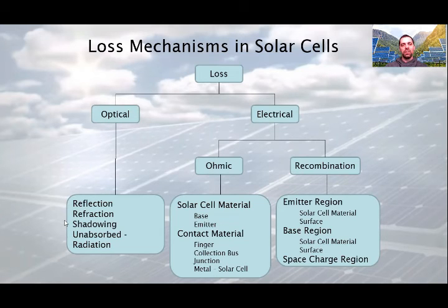Photons with energy higher than the bandgap generate excited charge carriers which transfer additional energy to the semiconductor material, the thermalization process, and heat up the photovoltaic device. This increasing heat decreases the cell efficiency.